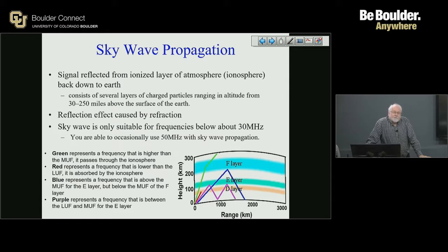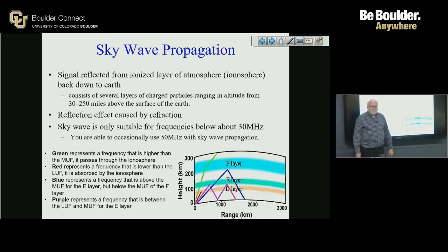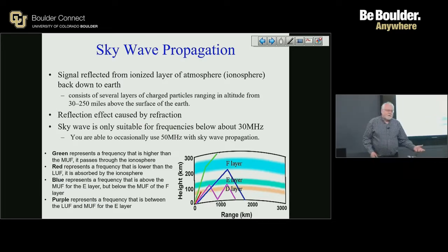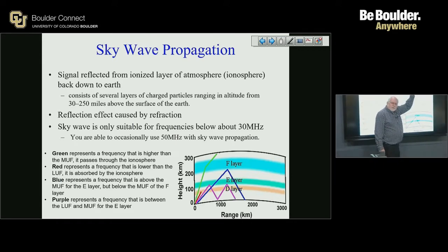For example, I think it's the Forest Service uses meteor backscatter even. As meteors come into the atmosphere, and there are always small meteors coming into the atmosphere all the time, they create ion trails. And anytime you have ions, that creates a charged boundary, you can bounce a radio wave off of it. So in remote areas where they're trying to monitor for forest fires and stuff, they can even bounce radio signals off of ion trails of meteors coming into the atmosphere. It's called meteor backscatter.